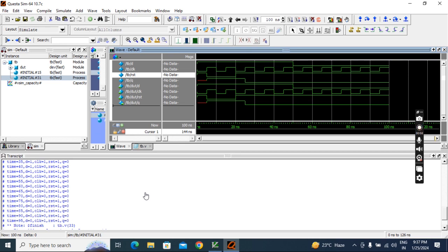I am not explaining the GUI mode or step-by-step manual process. It will take so much time. It's not the best way, because in industries we follow command mode only. You can follow this. The same process is applicable to ModelSim also. But when you are simulating in EDA Playground, you don't need to write any run file.